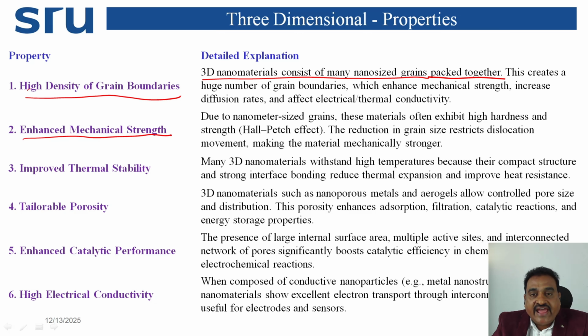Due to nanometer-sized grains, these materials often exhibit high hardness and strength, called the Hall-Petch effect. The reduction in grain size restricts dislocation movement, making the material mechanically stronger.